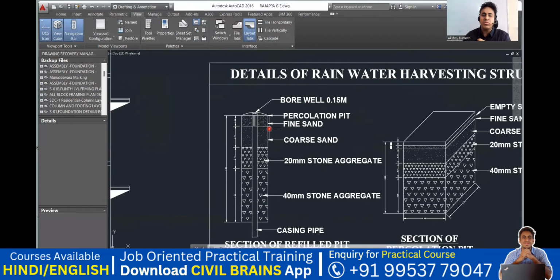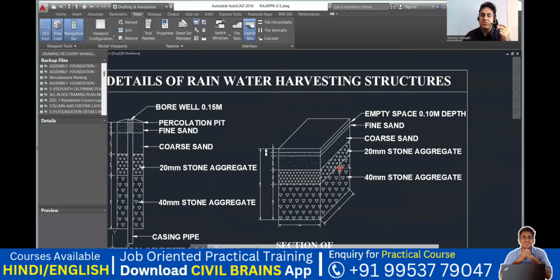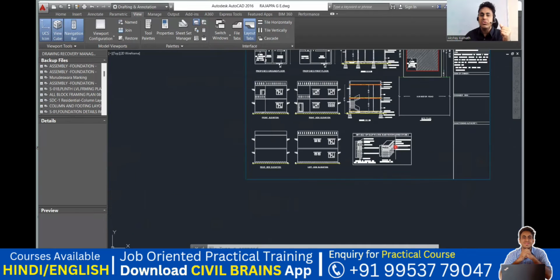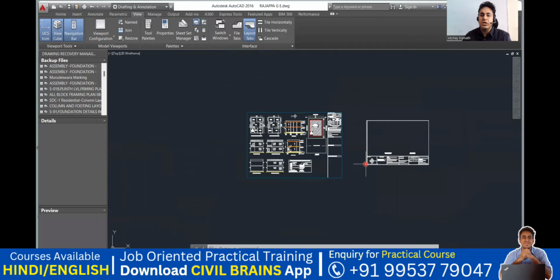So why is it in this way? Because your water has to percolate through that. Okay, your water has to percolate in this way. That is why we are going to put fine sand, then the coarser sand, then the 20 stone aggregate, then the 40 stone aggregate, so that if any dust is there, it remains here only and will not go to the bottom. Okay, so this is how a typical rainwater harvesting structure looks. You have 40 aggregate here, 20 here, a coarse sand, a fine sand, and this is an empty space of around 0.10 meter depth.